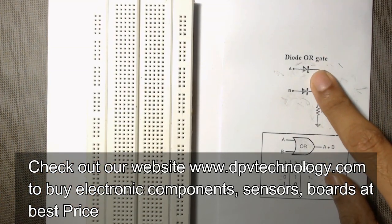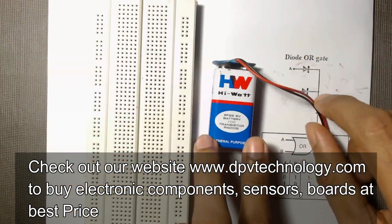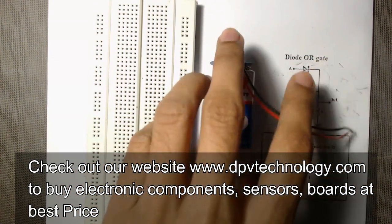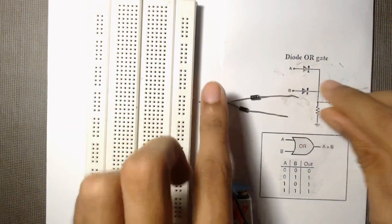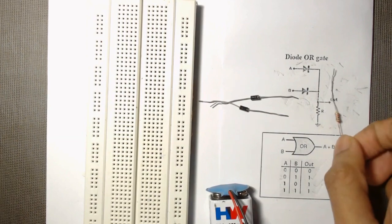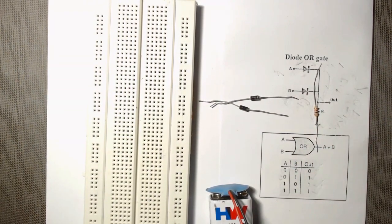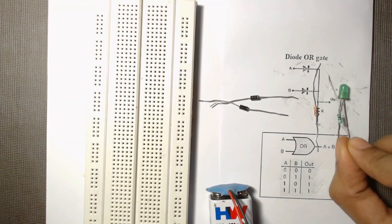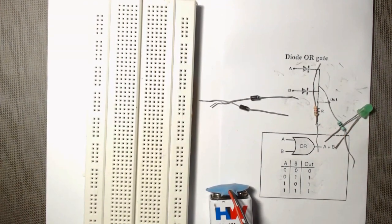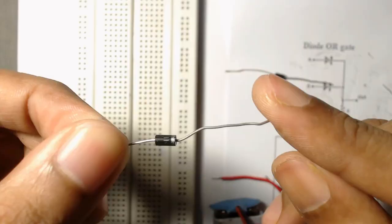For this project we need a 9-volt battery with clip and two diodes. Here I am using 1N4007 diodes and one 1K resistor. You can use any value. And one LED to observe the output, and to protect this LED we have to use a 100 ohm resistor, and some connecting wires and a breadboard.